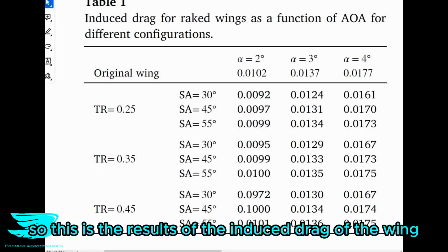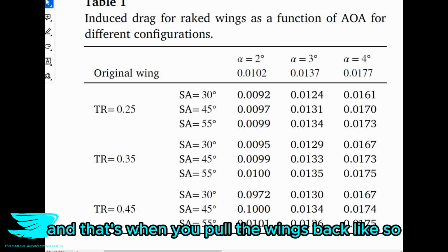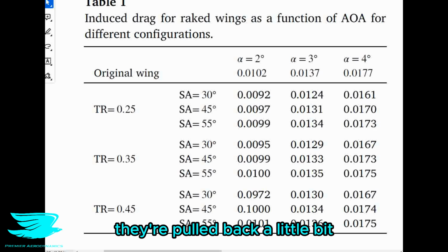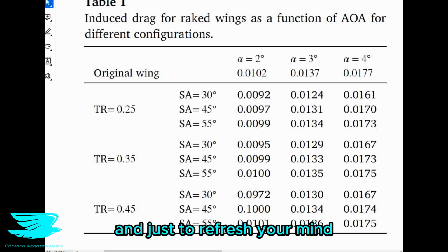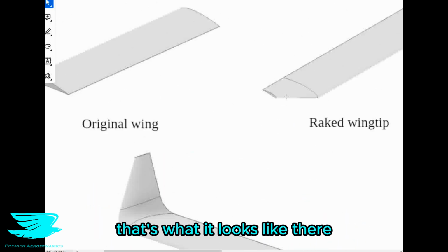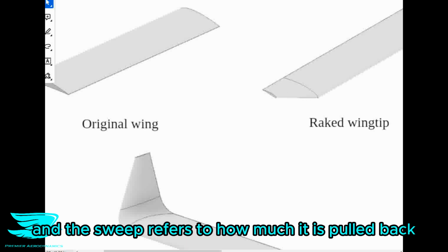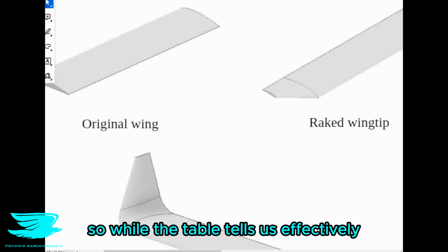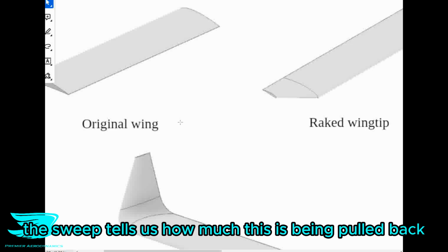This is the results of the induced drag of the wing with raked wingtips, and that's when you pull the wings back a little bit, and they have different amounts of sweep and taper ratios. And just to refresh your mind, in figure 1 we do see this raked wingtip just here. That's what it looks like there. This is the leading edge up here and the trailing edge at the back. And the sweep refers to how much it is pulled back. So while the taper tells us effectively how quickly it is shrinking towards the wingtip, the sweep tells us how much this is being pulled back.